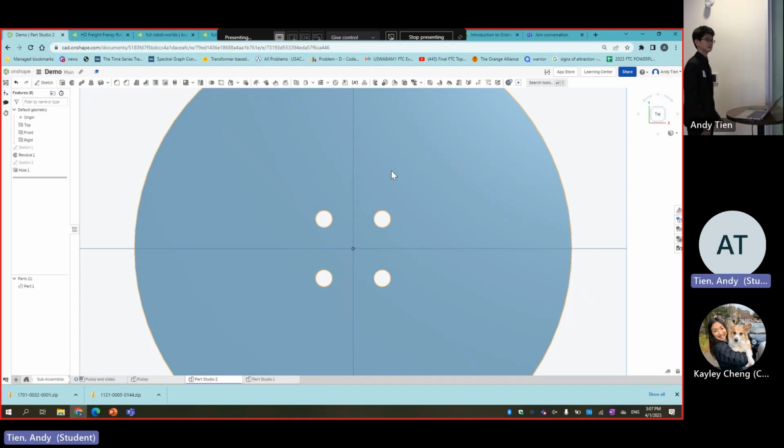So this actually comes with experience. I remember when I first started printing, I did 0.45 and it was too loose. And now for all my 4 millimeter holes, I go around 0.42. Really after 1 or 2 prints, you'll start to get it. You're just gauging the range every time you print until you refine it to a number that you're comfortable with.